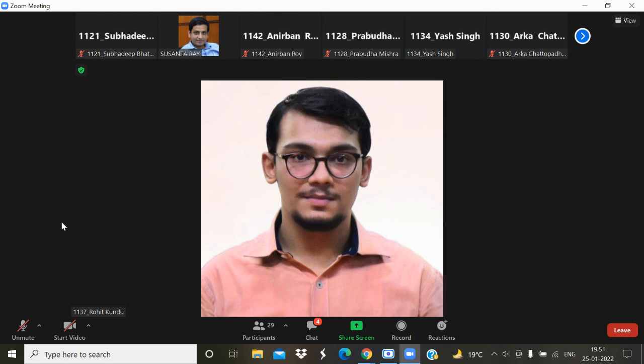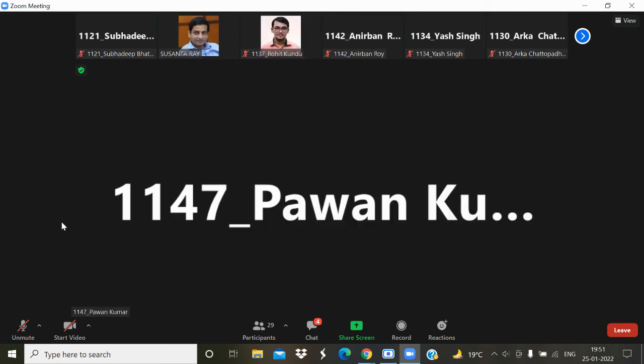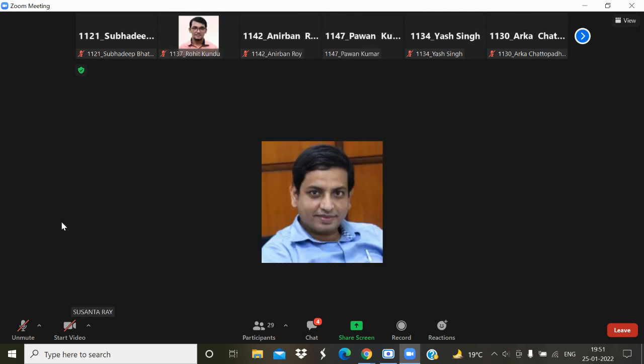Okay, so for my 170 kilowatt machine, 1000 RPM, I am getting diameter as 416 millimeter and length as 414 millimeter. These values are quite good. Sir, for 40 kilowatt, diameter is coming around 371 mm and length is 291.